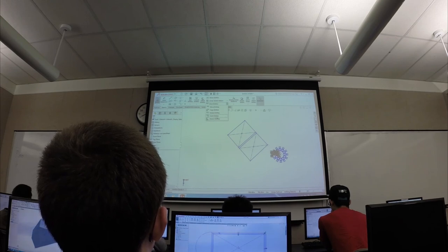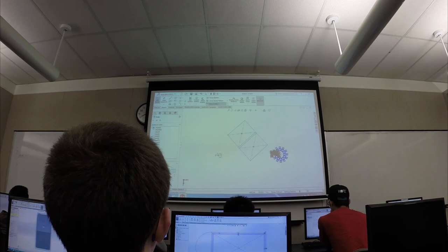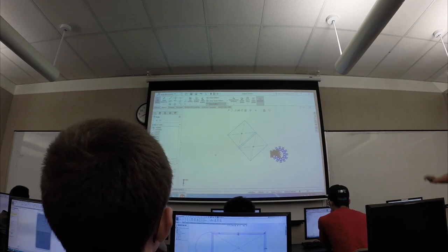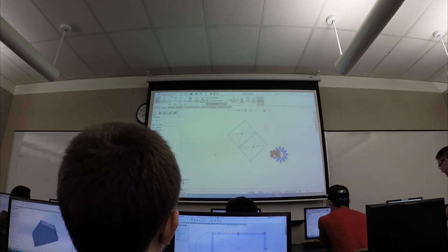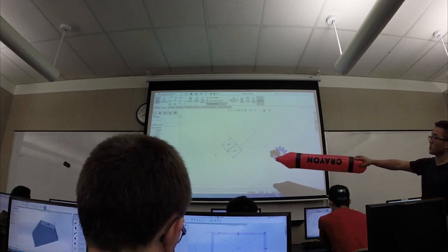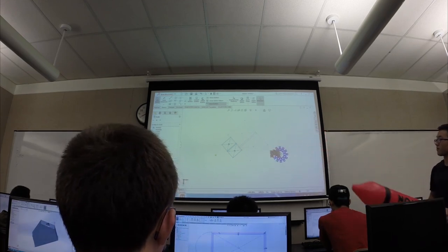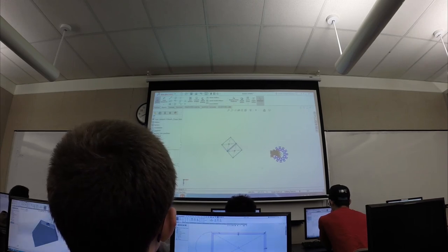So the last one we're going to play with is scale entities. Same thing. You select it, start about. So this is where your base point is. And say, okay, some random place in space here. And then it'll scale off from that point based by which multiple you have it by. So let's say, okay, multiply by half. We're going to bring it down by half. So it scales it down, right? With that point that you selected in space to be the center of where you're scaling it from. So okay, we're going to commit to that. Then let's see if we can remove this.